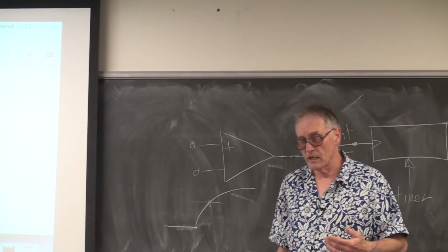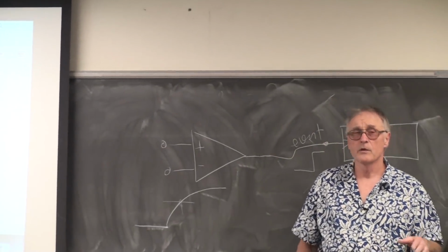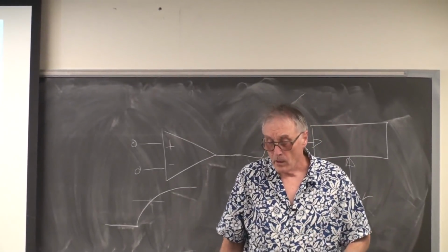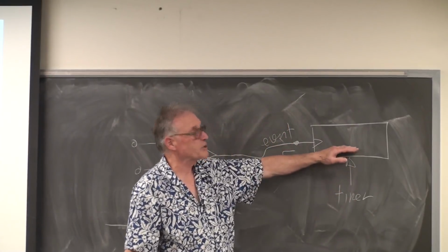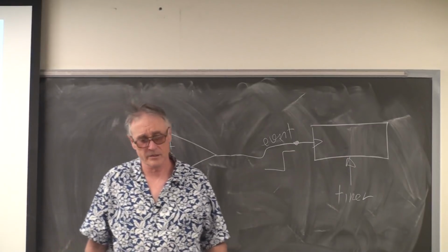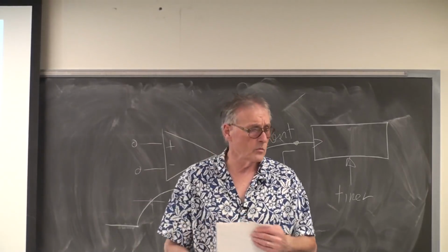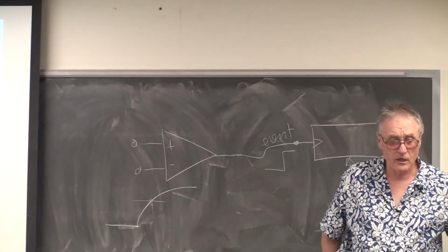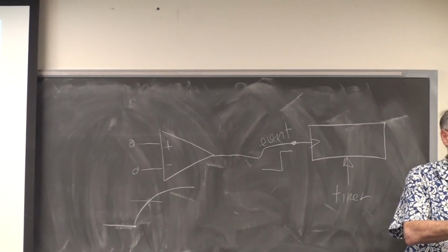And we're going to be using the PPS, the peripheral pin select system, to map signals to the outside world. And we're going to be using the comparator and an input capture channel to measure the time necessary to charge the capacitance. So if there's questions, I'll take questions. Otherwise, I'll go ahead and start talking about the horrible details of Lab 1. Questions?